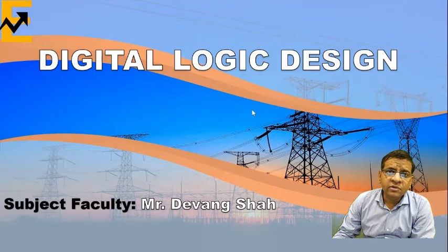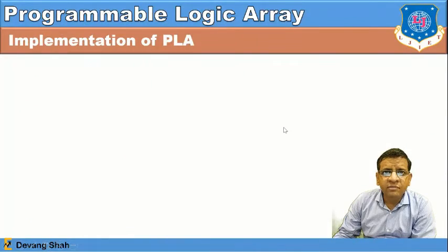So far in our previous session we have discussed programmable logic devices, where you found that any Boolean function can easily be implemented with a programmable AND gate and a fixed array of OR gates, right? As part of the PLDs, we have discussed the different types of ROMs, the variations like PROM, EPROM, EEPROM. Based on that, one step ahead, we are going to discuss the programmable logic array.